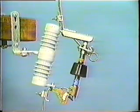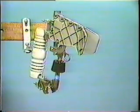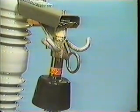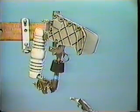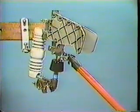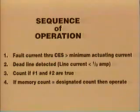Do not attempt to open a sectionalizer to interrupt load current without using a load break tool or a mounting assembly with arc chutes. The standard mounting assembly is equipped with hooks for use with a load break tool. For applications where opening under load is frequent, a load break sectionalizer is also available.